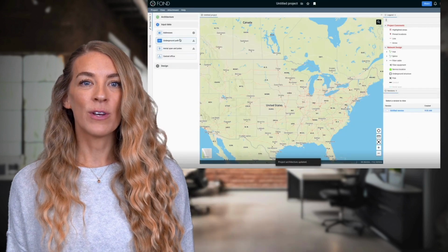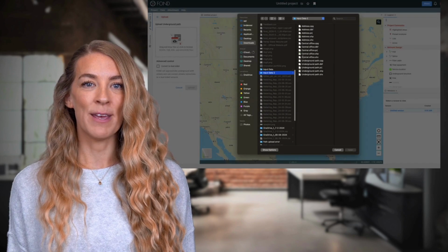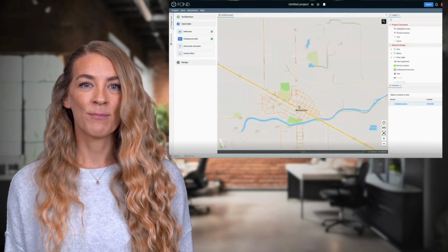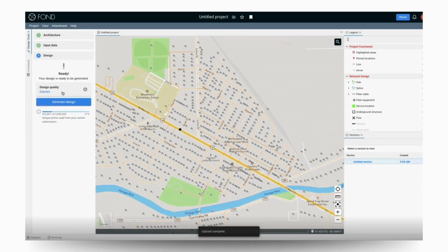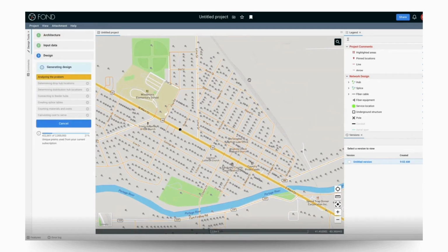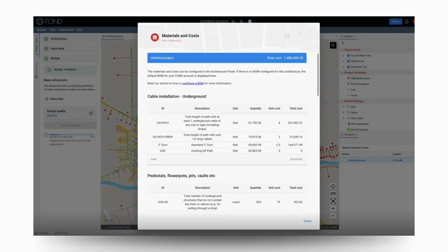Path scenarios help quickly visualize routes and estimate paths using the assigned labels. You can load street data and assign path types like aerial or underground. Once that's complete, you can map out paths to understand how each route interacts with existing infrastructure. This is helpful for differentiating between aerial and underground routes and understanding the resources and permits needed for different path types. Using these specific labels ensures effective separation of path types, which is key for managing costs, time, and impact.